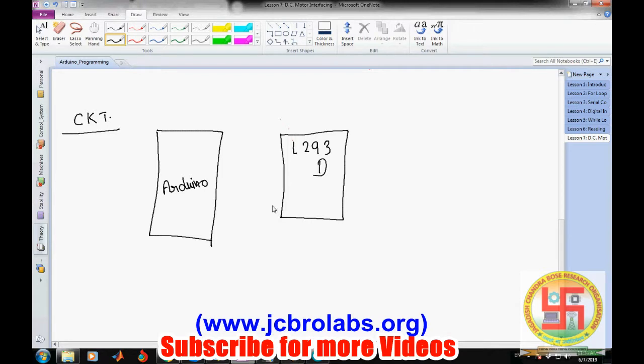As we talked about, pin number 1 will be connected to plus 5 volt, and pin number 16 will be connected to plus 5 volt, and then pin number 8 is connected to plus 12 volt. Now the ground pins are connected to ground. Similarly, there were 2 pins here, I think 13 and 12, and these are also connected to ground.